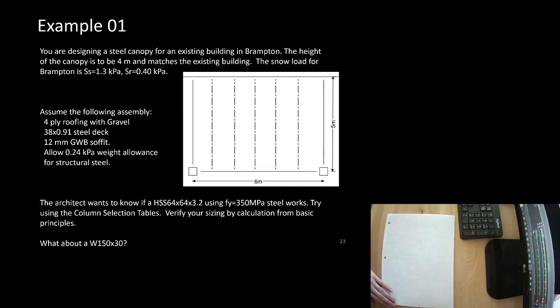Now I'm going to tell you that this is a really bad design because nobody wants to put gypsum wallboard soffit out in a real project outside because the underside of this canopy is going to be exposed. But we might give that feedback to the architect and they can do with it what they want.